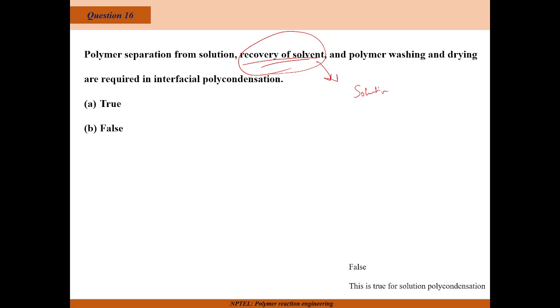So when we see solution polymerization, generally, say for example, I can convert a gas directly into polymer by bulk polymerization where I don't need any solvent. But the problem is that the reaction, as it propagates, will end up with very high exothermicity. So control of that reaction generally will be a problem. So there I can choose a common solvent where this gas reacts, because definitely when I use a gas, there should be an initiator. So the initiator will be in liquid phase and gas phase. I will select a common solvent where both will dissolve.